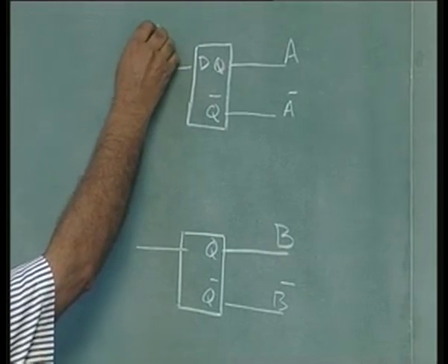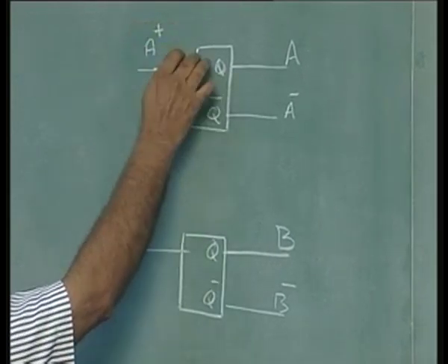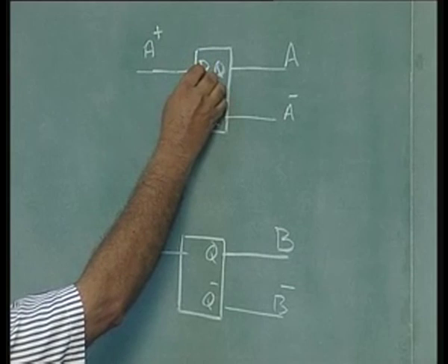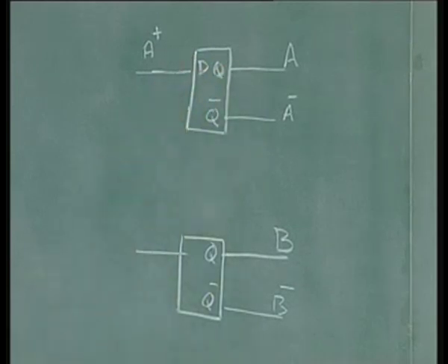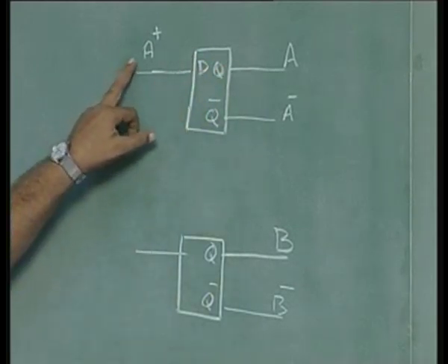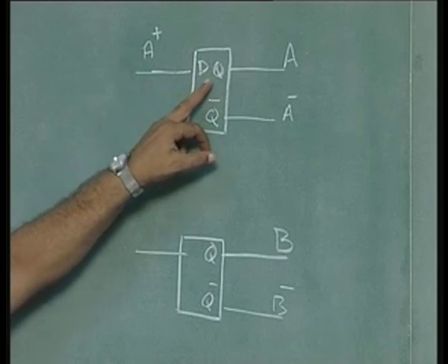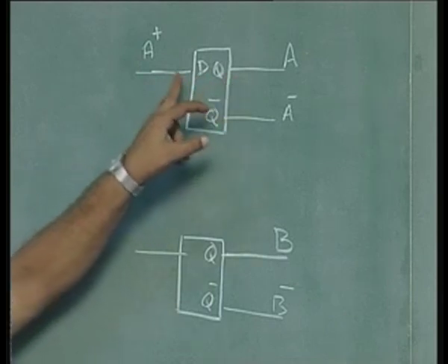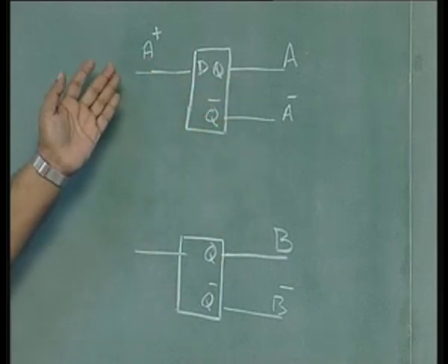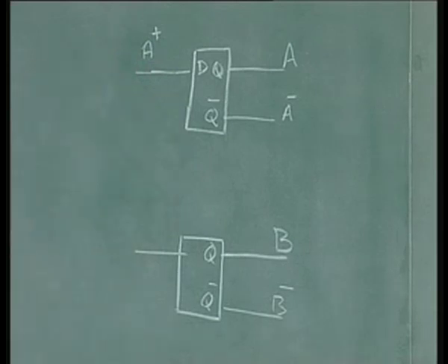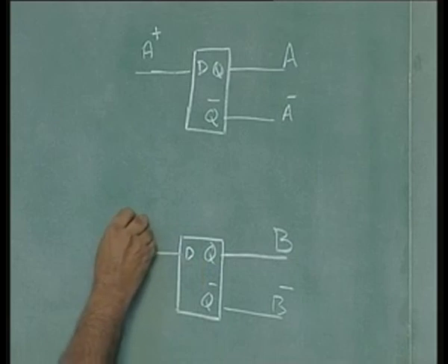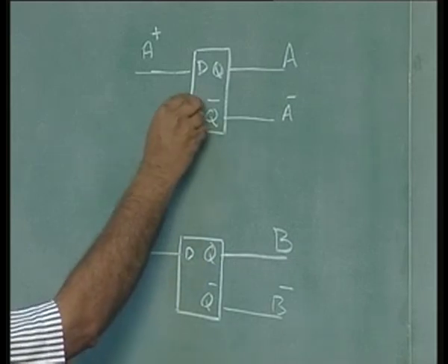The next state information will be for a D flip flop, the output follows the input. That means, if you give the next state information here, that will be taken as the present state when the clock arrives. That's why we call it A plus. If you want to call it DA, this is fine. Similarly, call this DB or B plus, driven by a common clock.